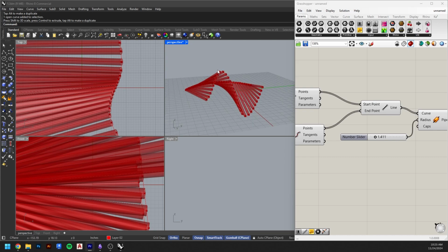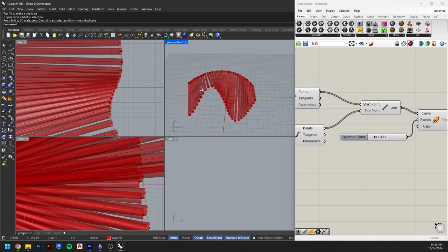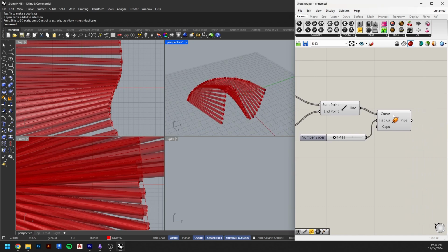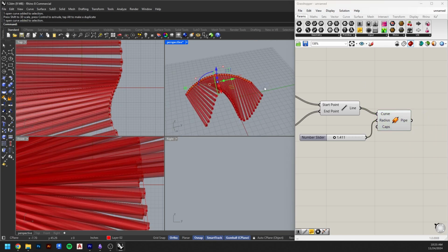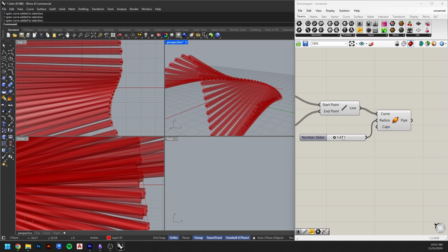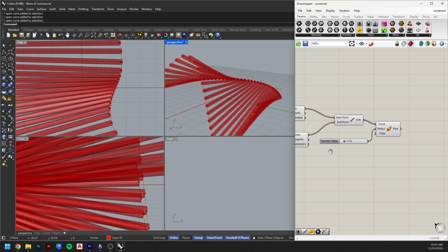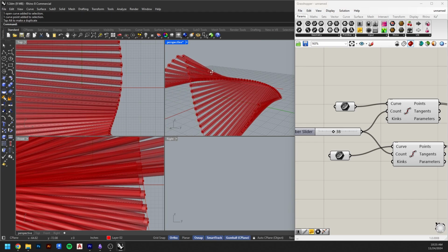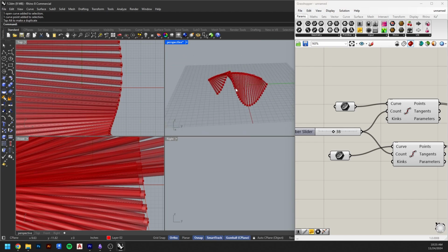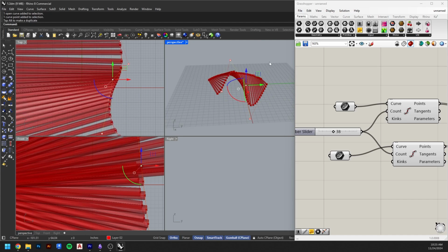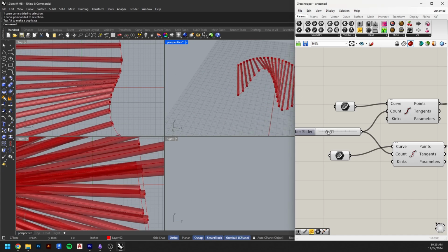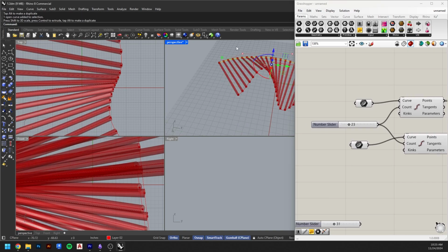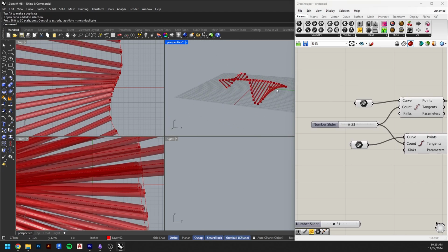One last thing that I left out, I want to touch back on this. Remember that all of these items that Grasshopper has created are ghosts, okay? They're not real. They're not really here inside of Rhino. The lines are here. We made those in Rhino, but these items are ghosts, and they will be ghosts as long as they're in Grasshopper edit mode and able to be changed and rotated and stuff like that. So I want to work in Grasshopper with all of these items being these ghosts, and I want to get my position right and get it to be how I like it and make all these edits and make all these iterations and changes.